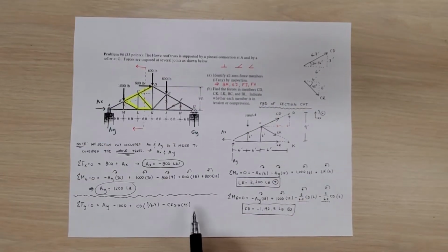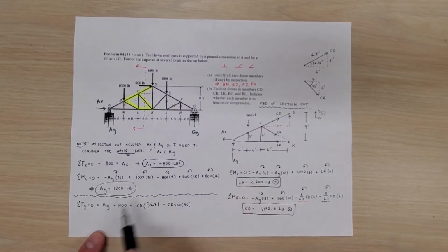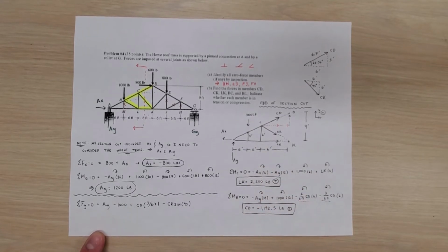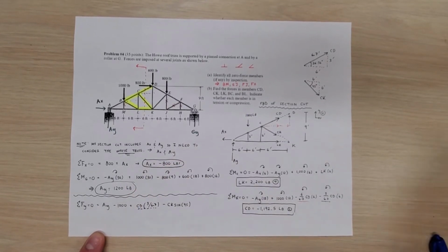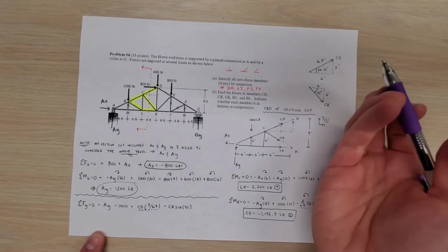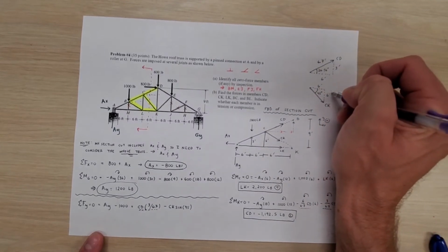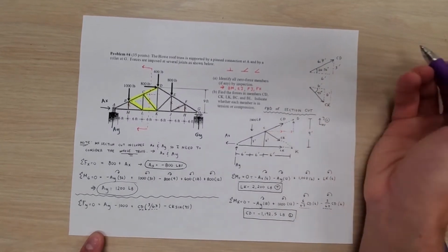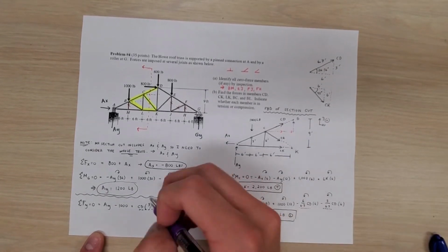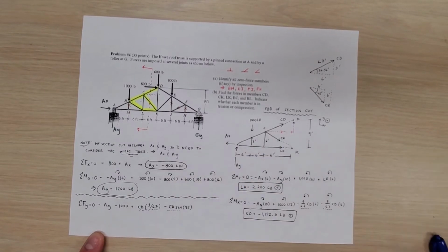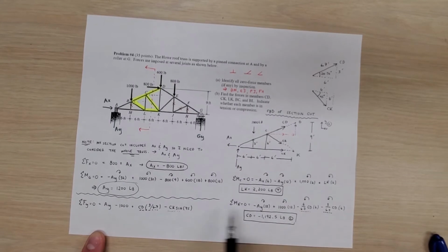So I've now set up the sum of the forces in the Y. You can see that we've got AY going up, which is right here. We've got the 1,000 pounds going down right here. We've got the Y component of CD, which I drew in blue. So I'll put that here. And then we've got the Y component of CK, which it doesn't really matter, honestly, because we have an angle of 45 degrees. Both the X and Y component are going to be the same. But we have CK times sine of 45, which I'll say is the purple component of CK. We can plug and chug all these numbers here because we already know CD from before.